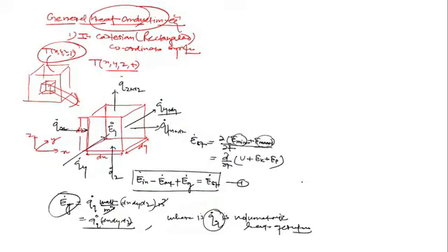My dear student, since the system is stationary, it is not moving anywhere, is there any change in kinetic energy? The change in kinetic energy is negligible. The system is not elevating to any position, right? So the system is neither moving, or if moving, then it's moving with constant velocity, so the change in kinetic energy is zero, and the system is fixed at a position, that's why the change in potential energy is zero. Then the stored energy is only del u upon del t.